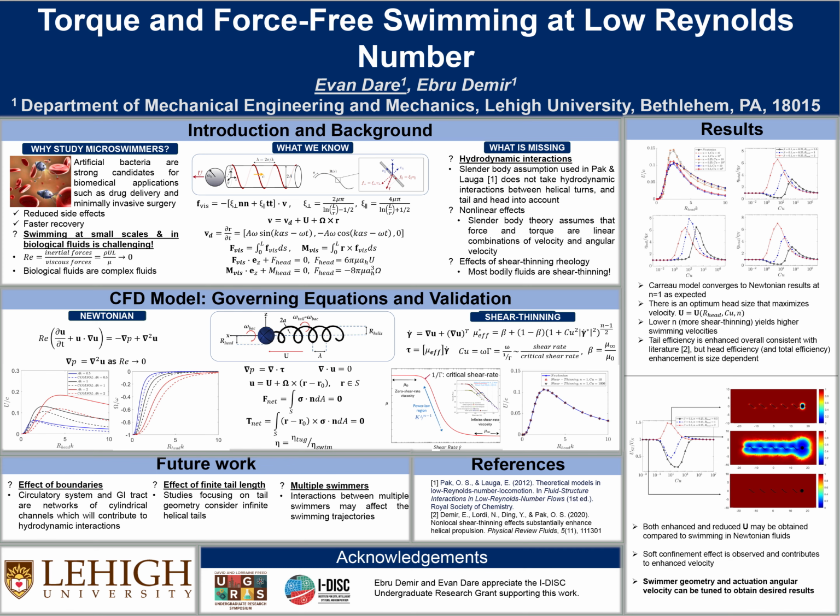As the length scale diminishes, the Reynolds number approaches zero, taking with it all terms involving time and leaving the so-called Stokes equation. Time can now only enter the system as part of boundary conditions, which do not affect the flow field. We compare our Newtonian simulation results with the analytical solutions from Purcell and Lighthill at 3 different tail radii for a range of head sizes, represented as R head.